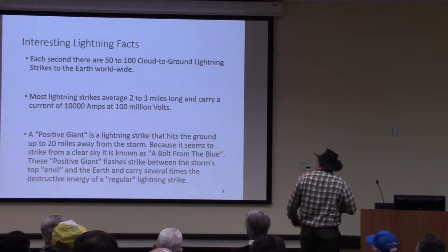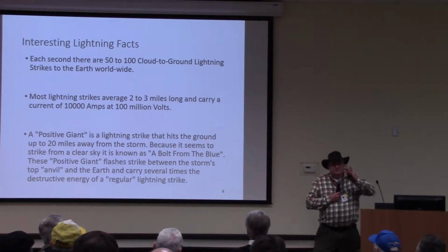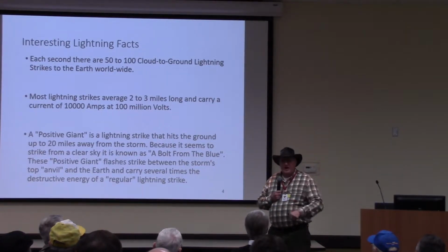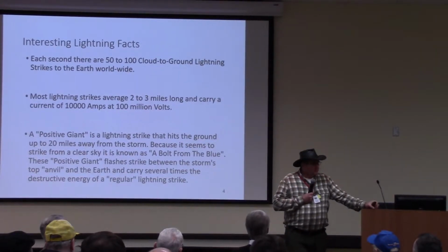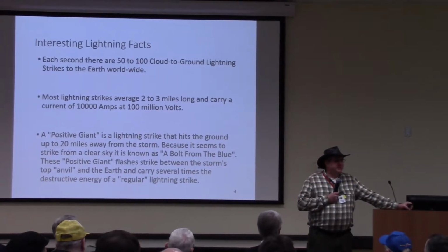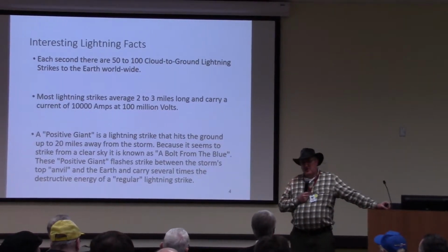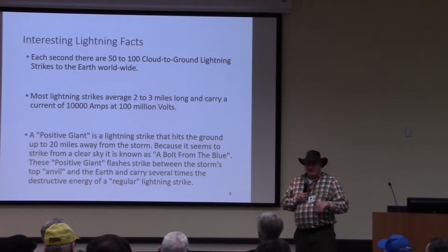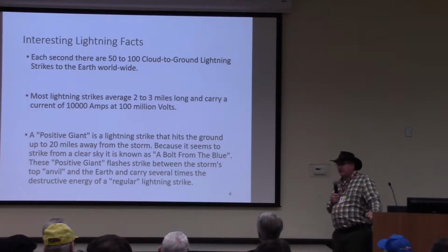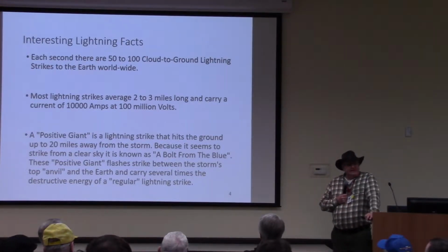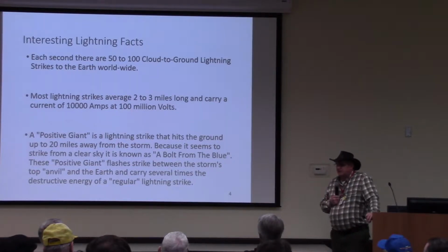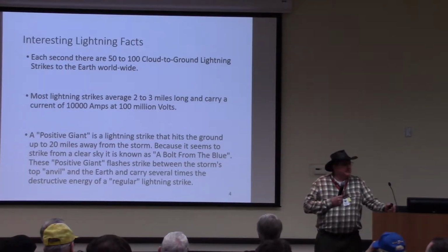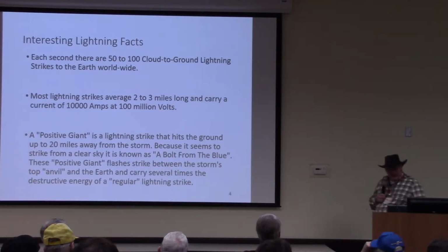Now the 100 million volt term, that's a little iffy, because that's dependent upon the dielectric strength of the atmosphere, how high it is above the atmosphere. And that is the potential prior to the strike. So saying there's so many volts in a lightning strike, that's just prior to. It'd be considered like an open circuit voltage, where there's no load on it. And then when the discharge occurs, it's like a short circuit current, or it is a short circuit current. So you're basically short circuiting that little circuit that's involved.